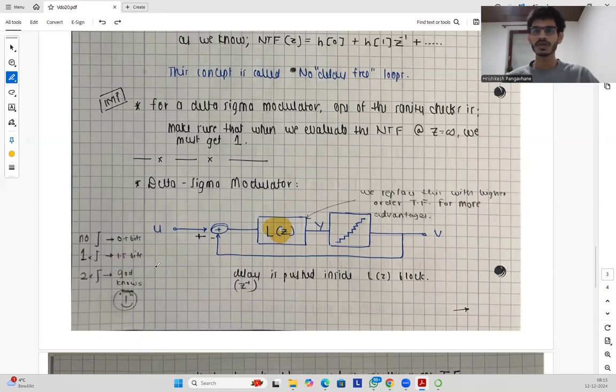What if we use two integrators, or nested compensations, let's say feedforward or Miller compensation for nested op amps? Then we will get even higher resolutions. Once we have proved this, we can go for higher orders.